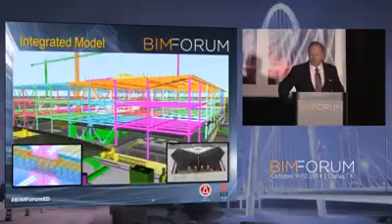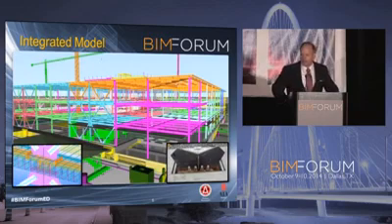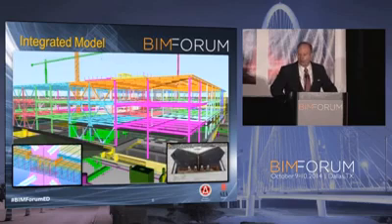In the lower left-hand corner, we had a difficult connection with some huge embeds. We were concerned about congestion. We knew that the anchor bolts had to be perfect. So again, we modeled everything. We modeled it as it was going to be built. We worked with the design. And you can see over in the lower right-hand corner, we came up with a more effective prefabricated insert, and the bolts fit.